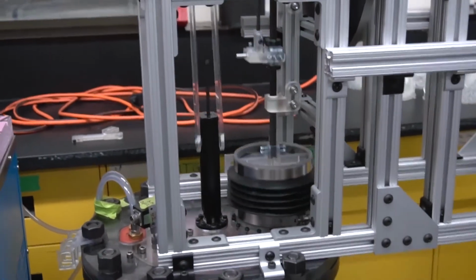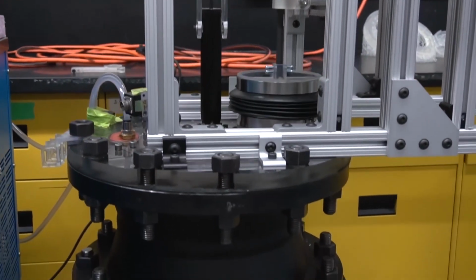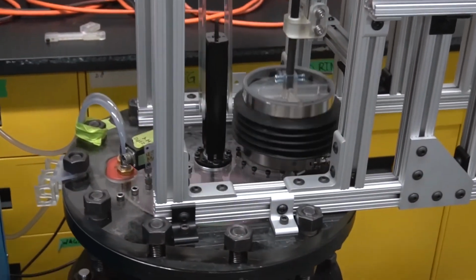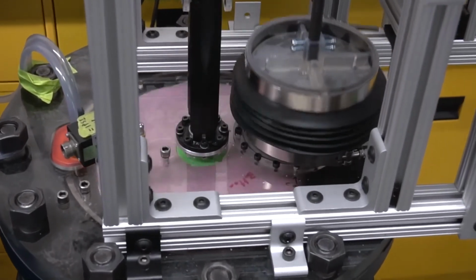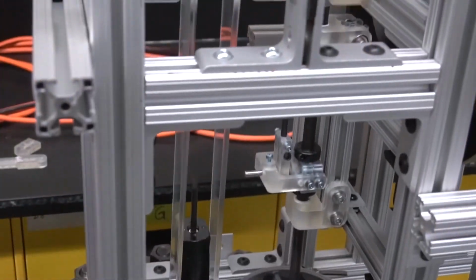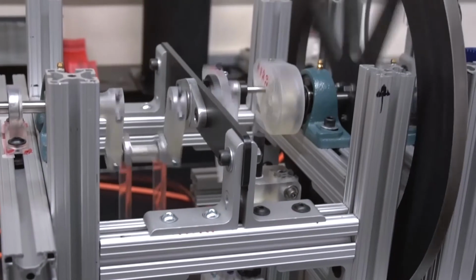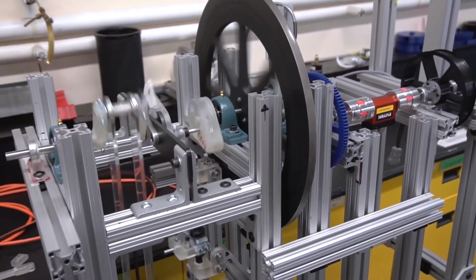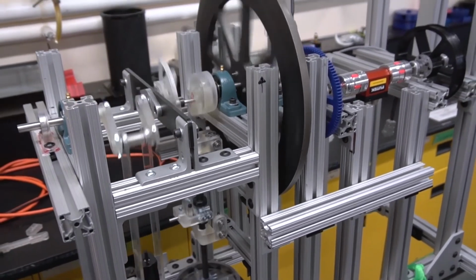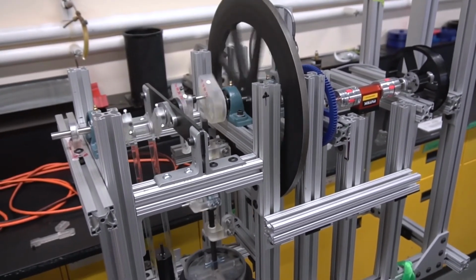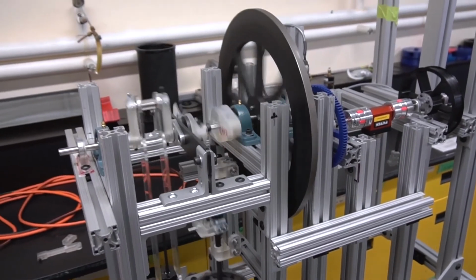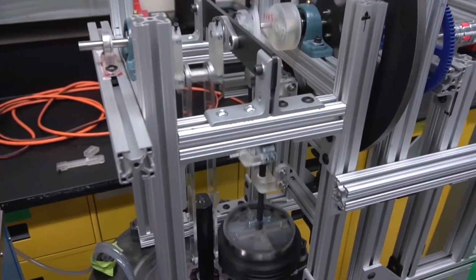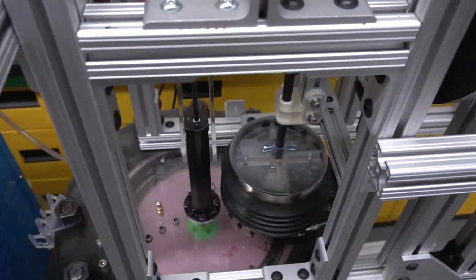So pictured in front of you is a Stirling engine. Stirling engines work by operating between a temperature source and a temperature sink to generate mechanical power. So here you can see two different pistons of a Stirling engine, one being the power piston and the other being the displacer piston. The power piston is able to move according to the pressure change inside the Stirling engine, and this in turn drives the displacer piston, which results in the fluid moving between the temperature source and the temperature sink, which generates the pressure change and in turn creates the motion of the power piston.